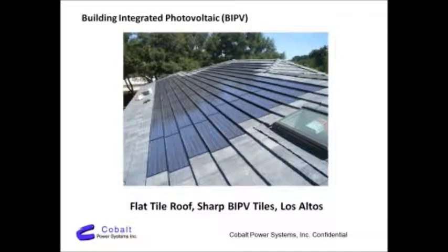There's also a type of solar panel called BIPV, which stands for Building Integrated Photovoltaic, and this is an example. We don't really recommend it. It's expensive, it's very labor-intensive to install, and it's low efficiency. And one of the reasons it's low efficiency is there's no air circulation underneath the array, which causes it to have lower efficiency. But sometimes people ask about BIPV, so I thought I would show an example.